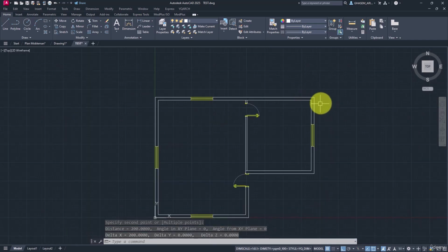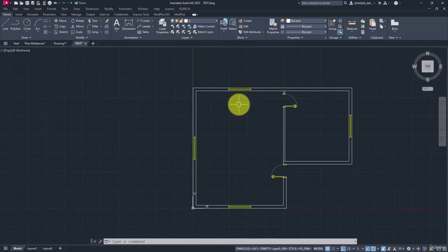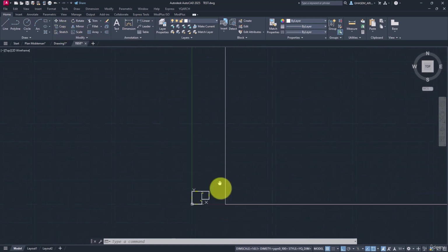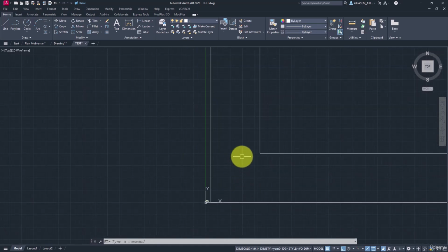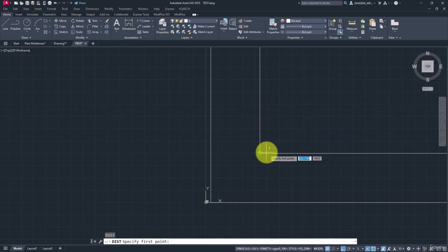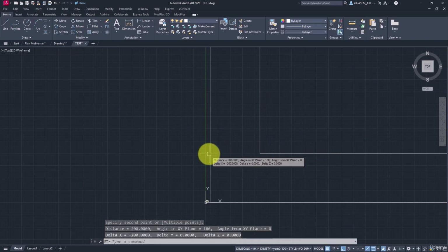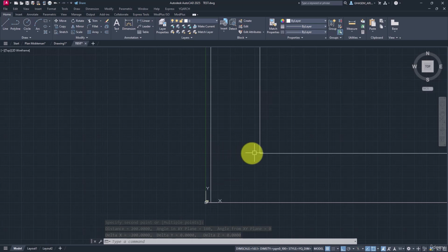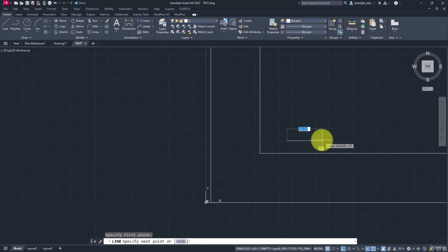And right now, if we import this into Revit, we'll have some difficulties and problems. So how can we fix it? We should scale it to minimize or resize it, or it's better to use align. My recommendation is align. Firstly, I make sure that the thickness is 20 centimeters, since we're going to consider it a reference to make sure that the thickness is 20 centimeters.